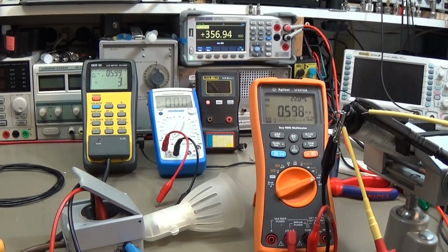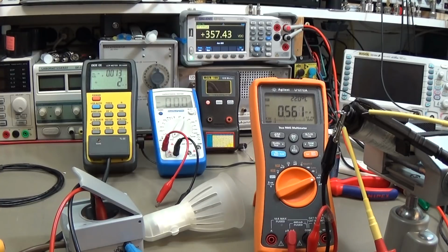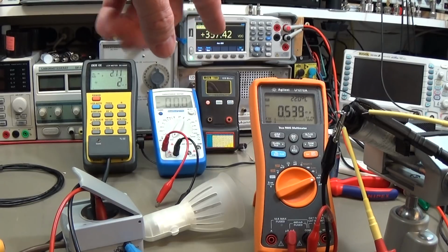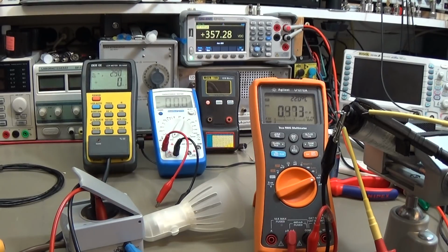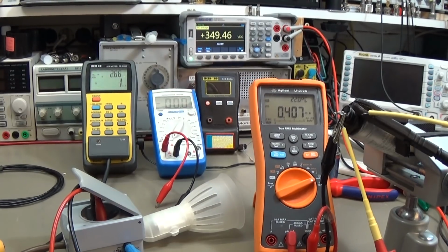And so we leave it run a little bit. I stop it now. If there would be a breakdown inside our capacitor, remember, our bulb here would jump in and would protect our circuit so that nothing can get destroyed, okay? By the way, what we are seeing here as well, our voltage is going up, and that is because our leakage current is dropping down. So let me adjust it a little bit back to 349, and we are at 40. So I stop it now.